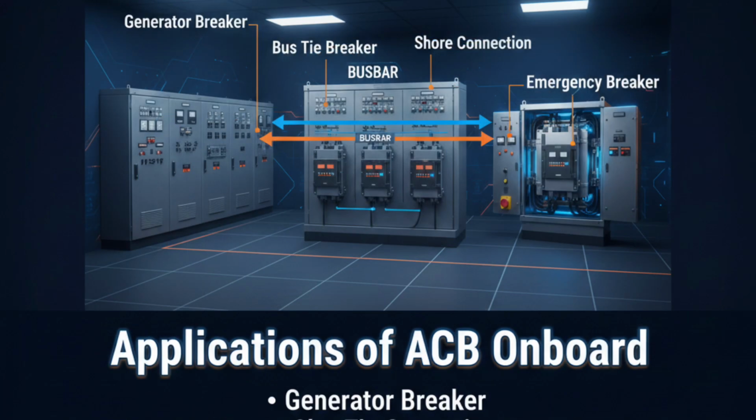Applications of ACB on board. Here you can see different ACBs inside a switchboard labeled as generator breaker, bus tie breaker, shore connection, and emergency breaker. Each ACB has a different responsibility. Generator ACB connects the generator to the main bus bar after synchronization. It must handle full generator load and fault current.